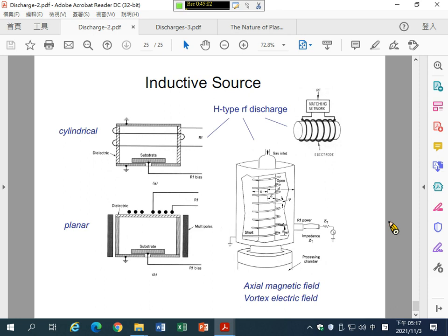At high temperature, the glass will become soft before it melts. So if you apply very high pressure gas inside, since the quartz becomes soft, it will distort. That is something you need to be aware of.